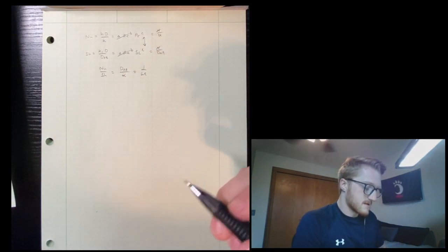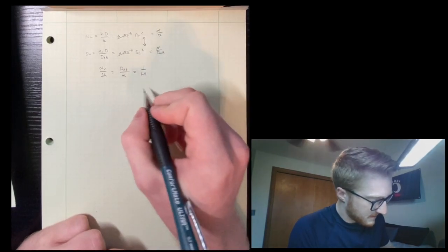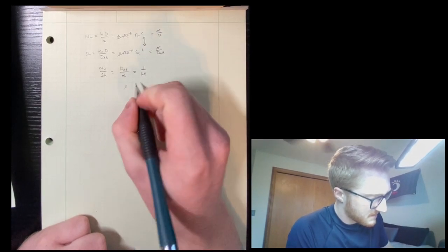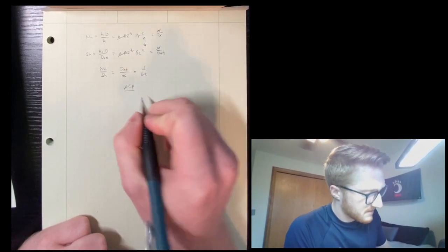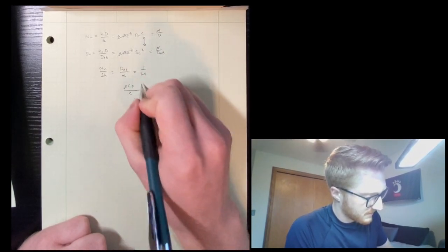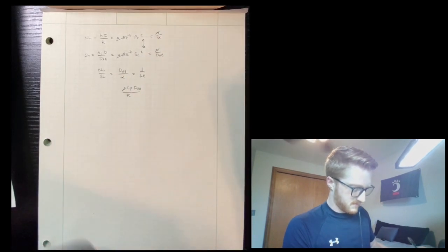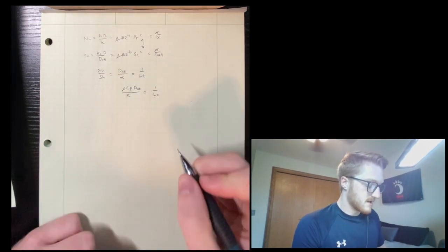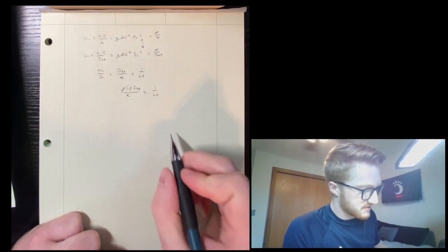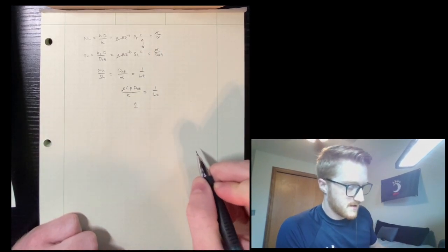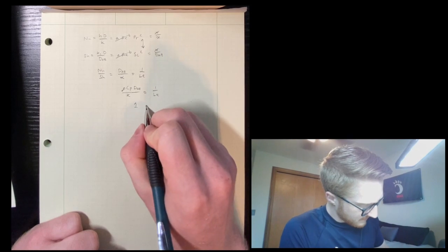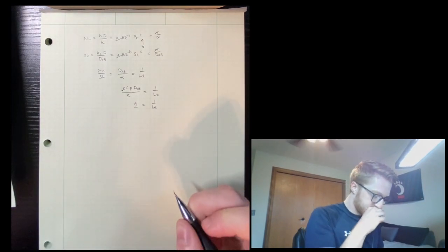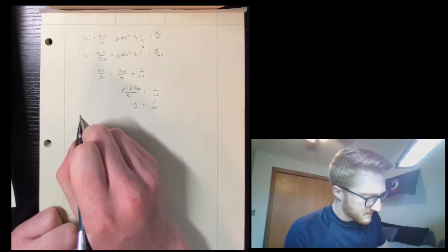And if we're looking at a system with moist air, we know, well, let me derive. So the thermal diffusivity can be rewritten as the thermal conductivity over the density times the heat capacity. And we're going to throw in our diffusion coefficient. And so if we have that as 1 over the Lewis number, for moist air, the numbers for each of these is going to actually end up equaling about 1. So we know that the Lewis number relation for this is going to be 1. And this is going to be important going forward, but we're going to rewrite this again.